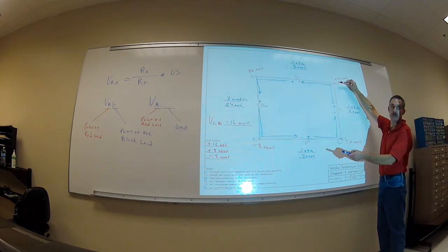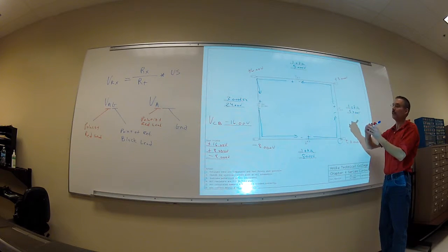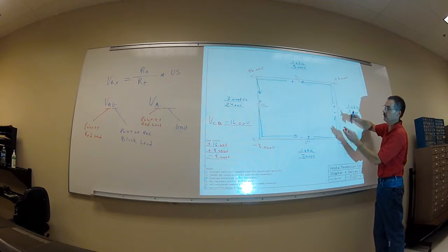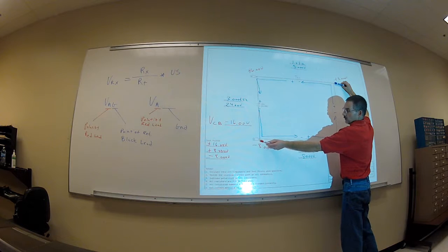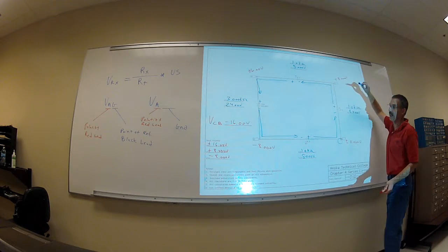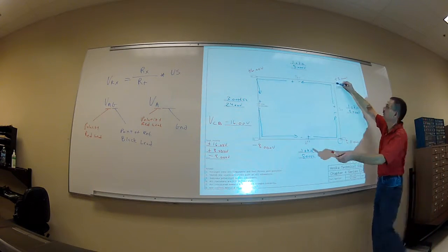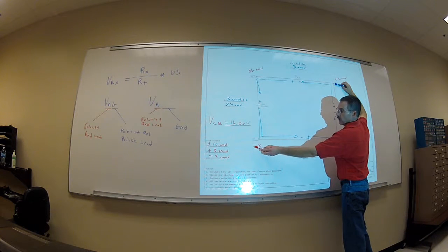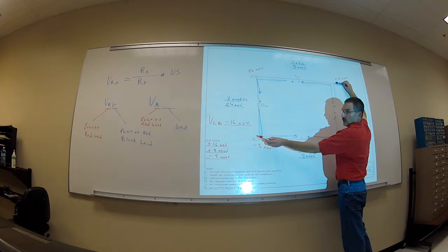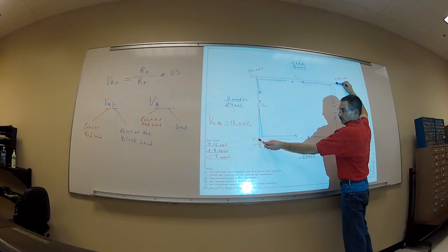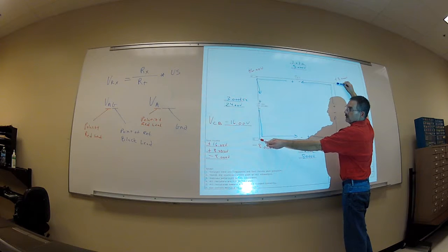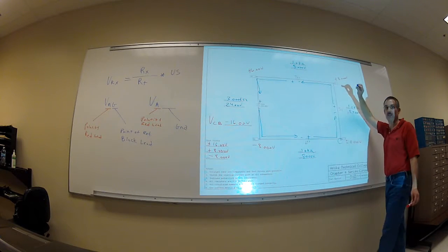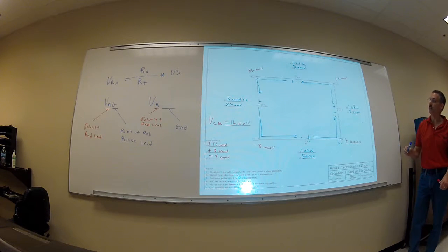Okay, so look at it as a number line now. It should be C to B, so it'd be plus 16 volts. Or not plus 16 volts, because my red lead is on a more negative number, right? My black lead's on a more positive number, so it's going to be inverted. So the potential difference between test point C to B is going to be negative 16 volts, okay? You don't always have to bring your red lead to your black lead.